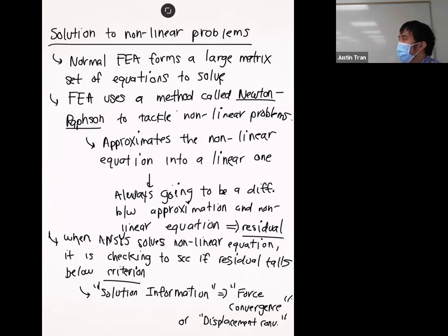Right. So I know a lot of this section is kind of hand wavy, but the point is, I want to show you what this force convergence is, what this displacement convergence is, just so that you can check and assess how accurate or how well solved your nonlinear simulation is. Okay. All right. Any questions on this? Okay. And so if you check those convergence plots, it might look something like this. Okay.